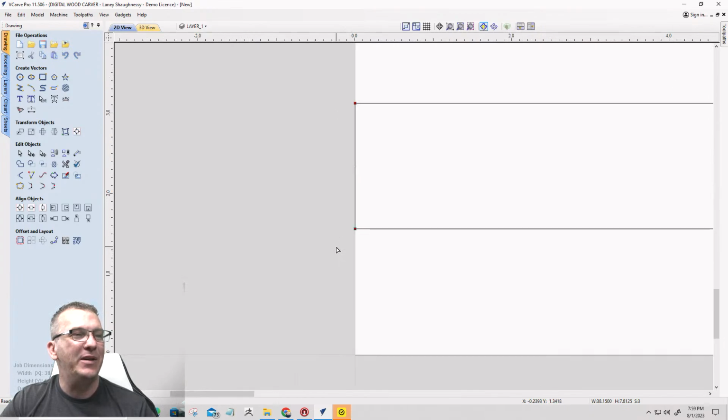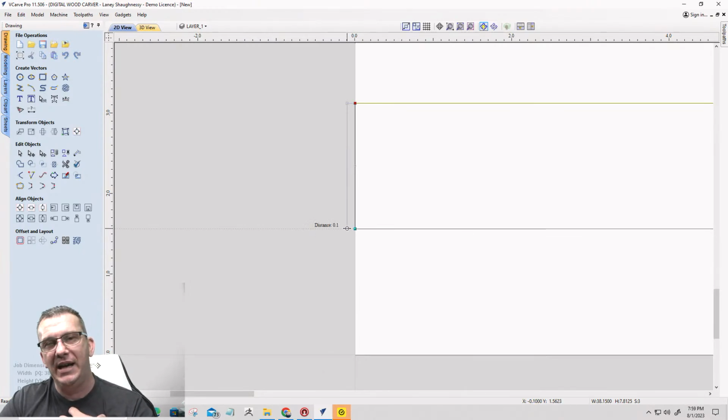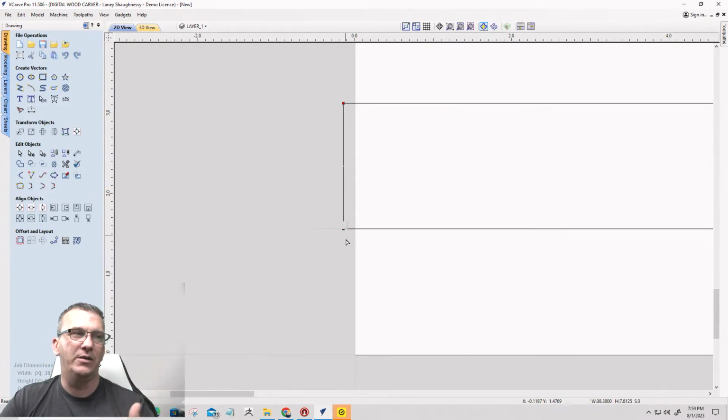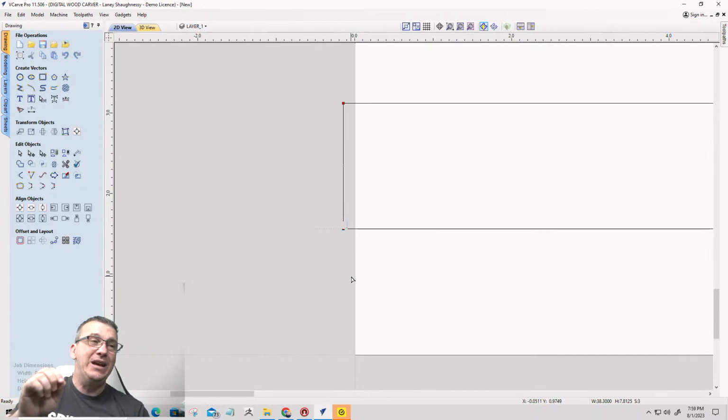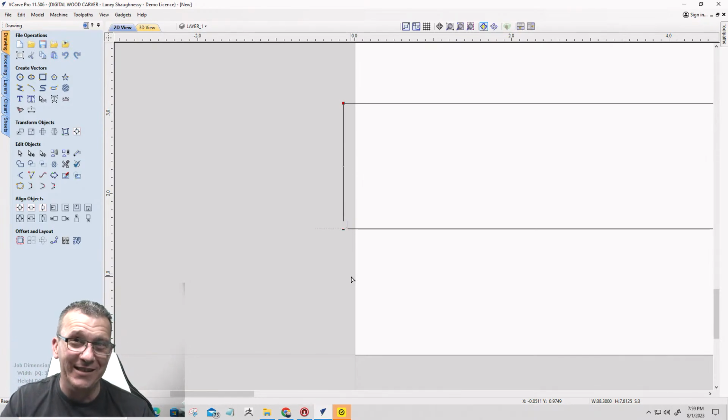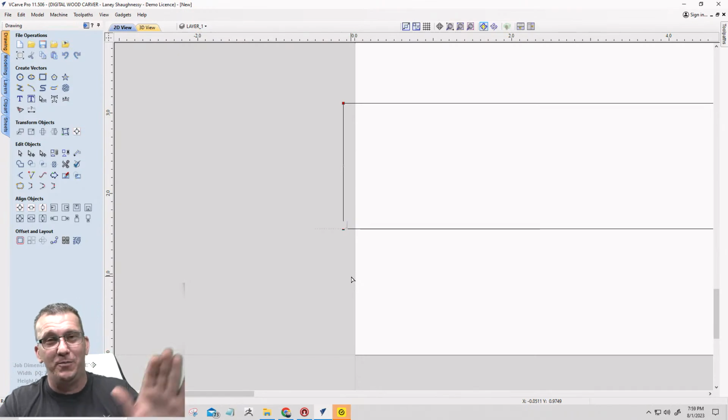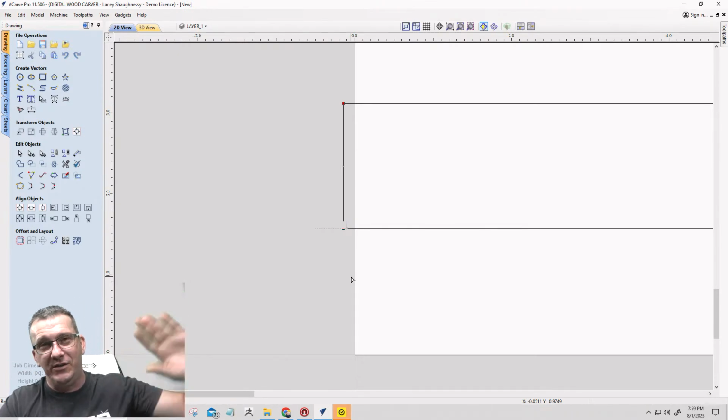And again, I'm going to do the same thing. I'm going to put my mouse over one of the selected nodes, pull that node out, and then type in a number, 0.15, and hit enter, and it's going to move it out that distance. It will move those nodes in whatever direction I pull them by that distance. So if you're pulling the node at an angle and you tell it to move an inch, it's going to move an inch. It's going to shoot it up an inch.